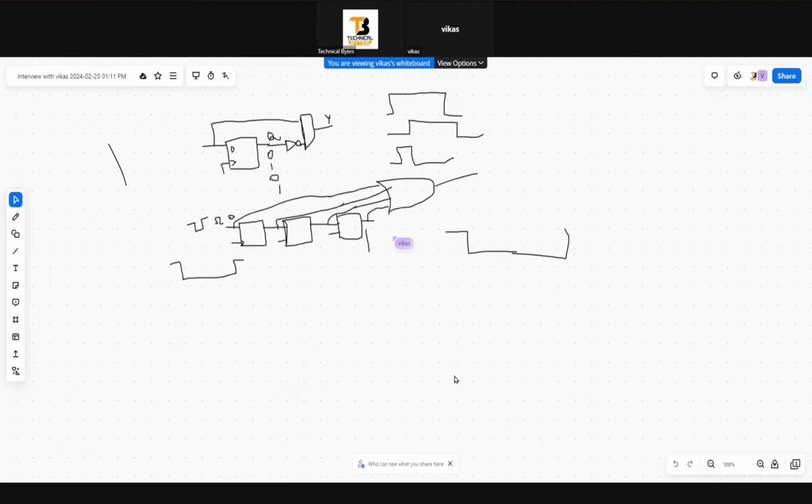Okay, if my input is a 3 clock cycle pulse and I want to make it 1 cycle, what will be my logic? This same logic can be used, no, sir? Delay that input signal by 1 flop and then use this. You are right. Good.